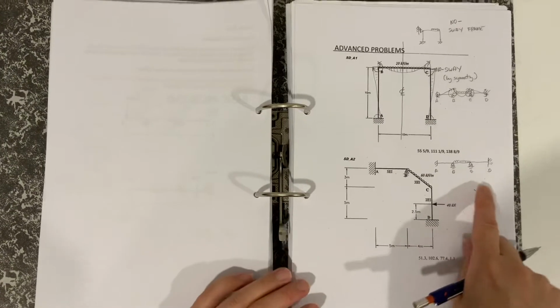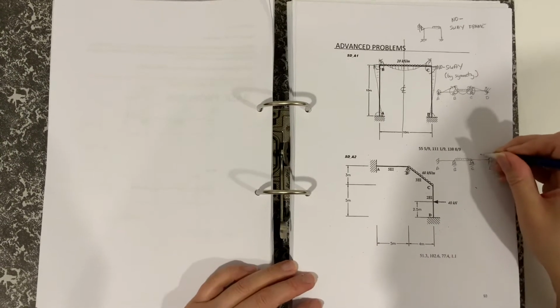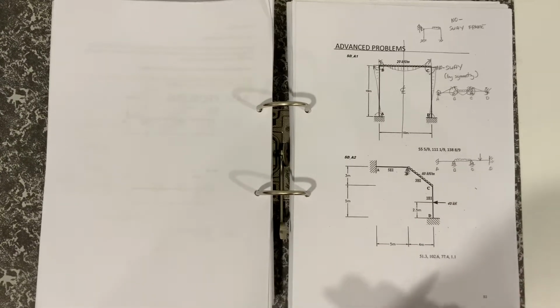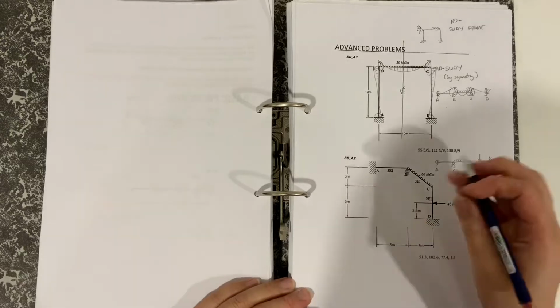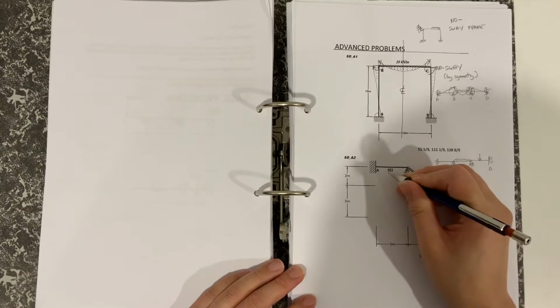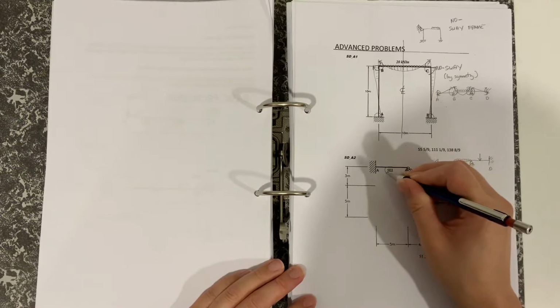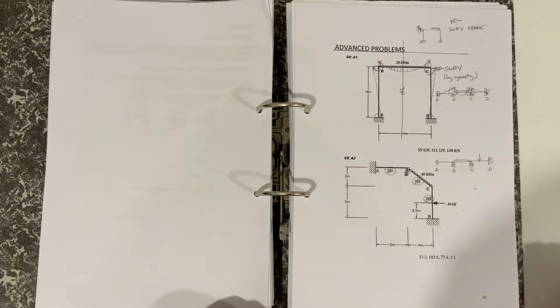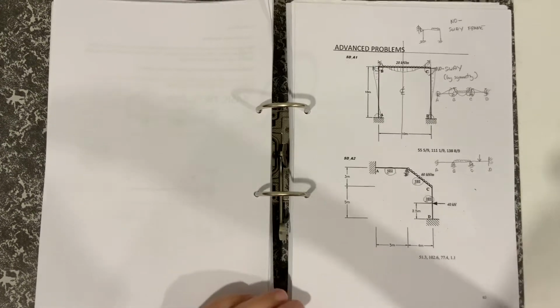So that's part of one of the problems that you'll be dealing with in this case here. And the other problem relates to the fact that this is 2, this is 3, and this is 5. So this is the bending stiffness. So the bending stiffness of each member is not the same.